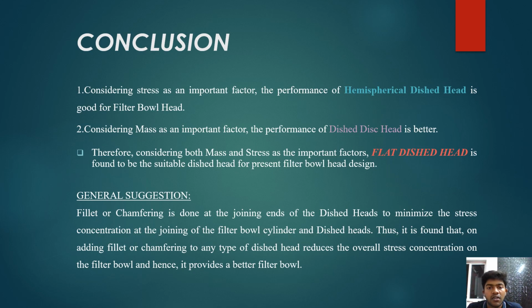So based on the results, the comparison of the results and the discussions, we can arrive at specific conclusive points. The first one is, considering stress as an important factor, the performance of the hemispherical dish head is good for a filter bowl head, but when it comes to mass as an important factor, the performance of the flat disc head is better.